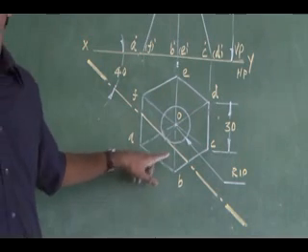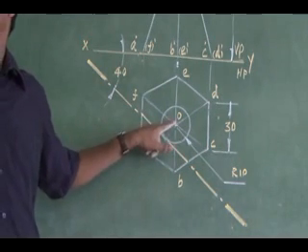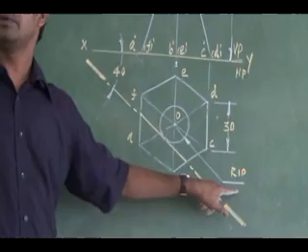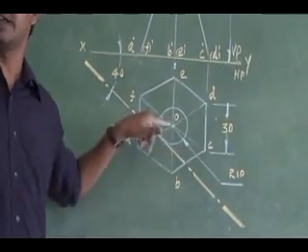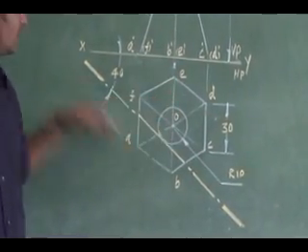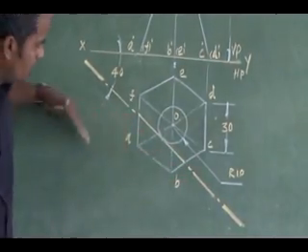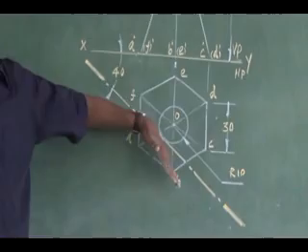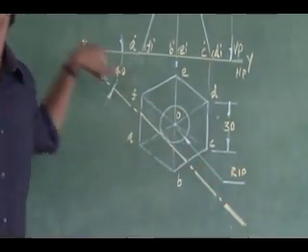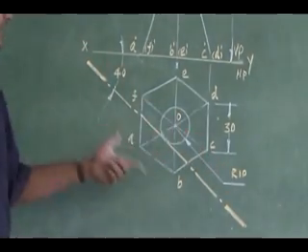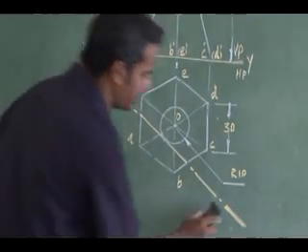So to represent the cutting plane, you draw a construction circle of 10 mm radius, that is the away distance. Then for that circle, you keep your drafter tilted to 40 degrees, move your drafter tangent to that and draw a cutting plane. Represent a cutting plane like this. Neatly you represent a cutting plane.